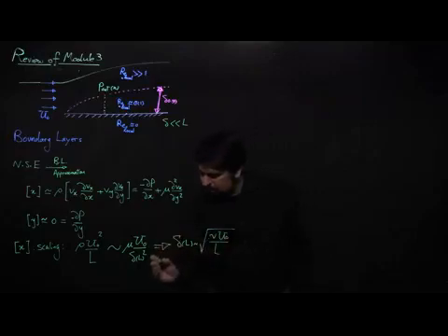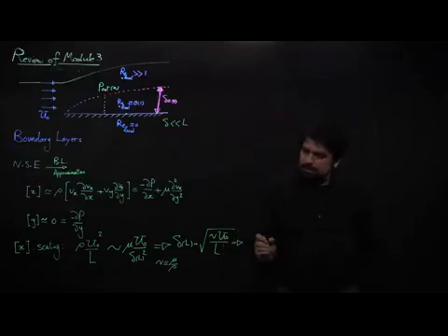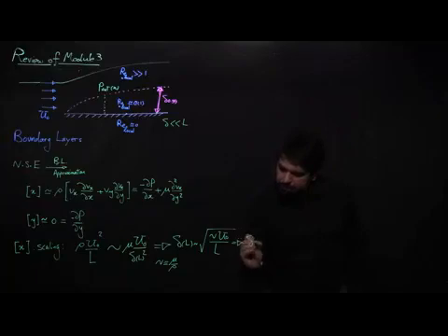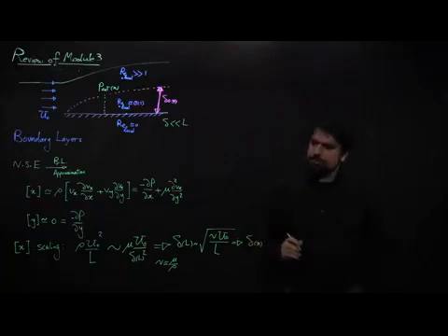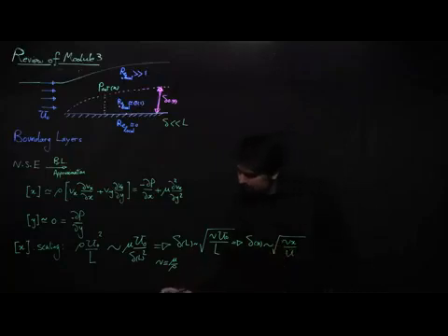So again, if you have forgotten, kinematic viscosity or nu is the dynamic viscosity or mu divided by density, which is rho. We could also take L out and write this scaling for a general position x. So delta at a position x along the plate is scaling as a square root of nu multiplied by x divided by, and I think I'm making a mistake here.